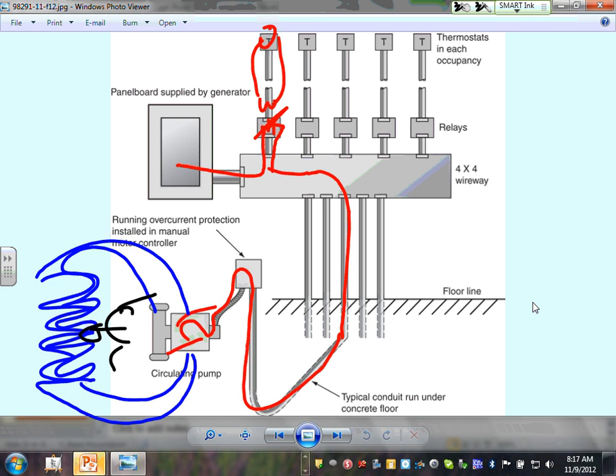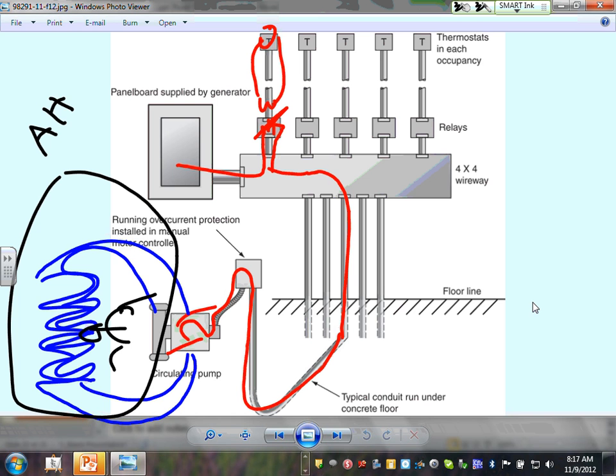What happens if you throw air through a hot coil? What happens on the other end? You get yourself heat. Unless you have radiators, which don't have a fan. But typically, all this junk that you're looking at here, this is what we call an air handling unit. Remember that air handling unit business? It brings water to these water coils. Inside it are big blowers that blow air through these coils. You've got yourself heat for your building.